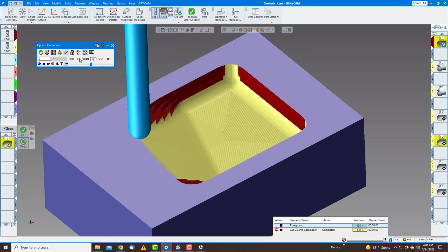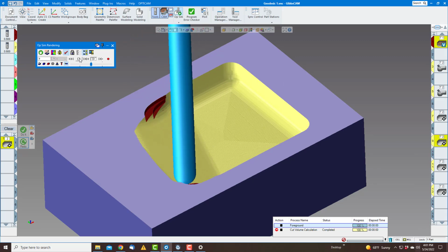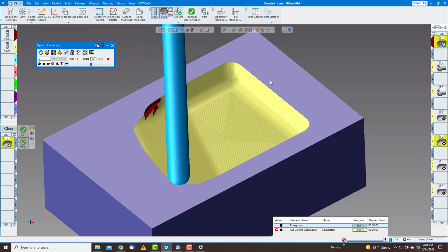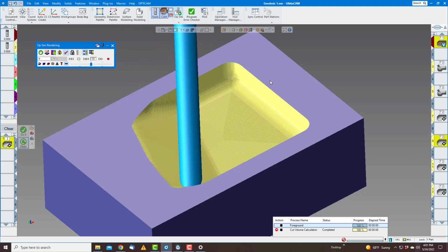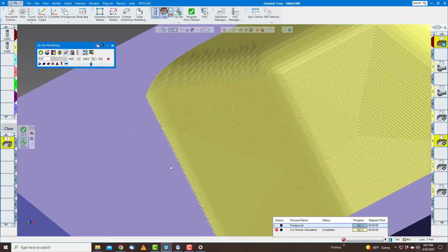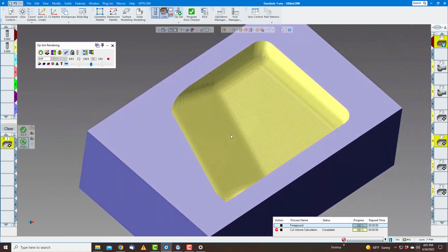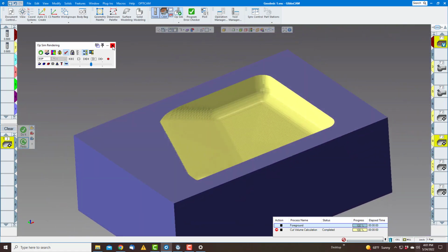And we're going past the boundaries by about 20 thou. So if you want to kind of clean up the edges here, that's a good toolpath to use. You can see I went past the boundary just a little bit. It's a little jagged here because I have some pretty coarse settings on here, but you get the idea.